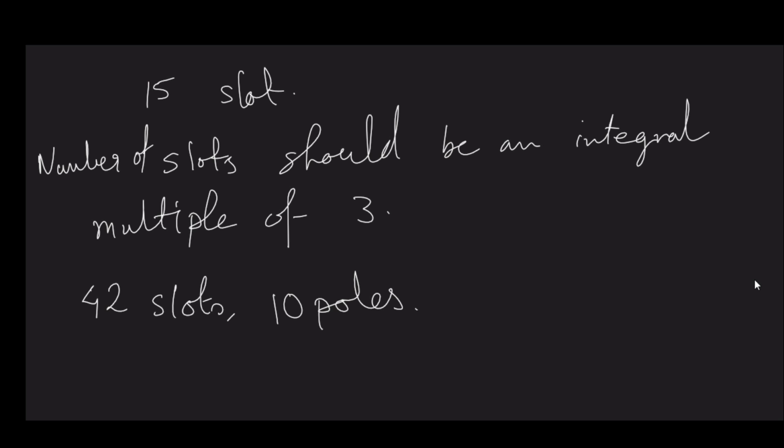Obviously it is 3 phase, so we have to figure out how to do it, and also single layer. Fortunately it is single layer. Had it been double layer, we will develop double layer, no issue, but for the time being it's single layer. And obviously we will look for a full pitch case. One question that can also be asked in this regard is, can we develop a short pitch or corded winding, that I have discussed in my last video, with a single layer winding? Think about it.